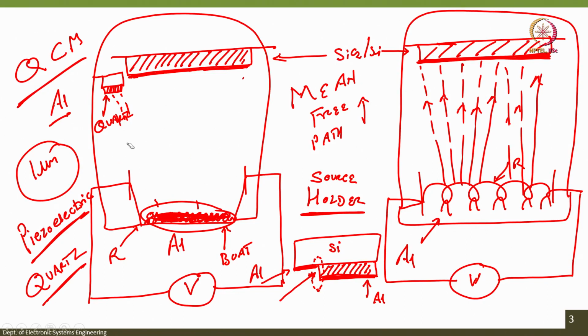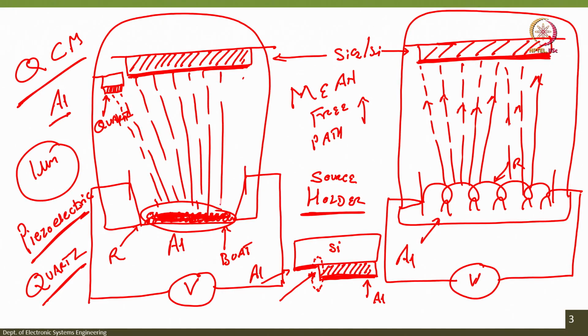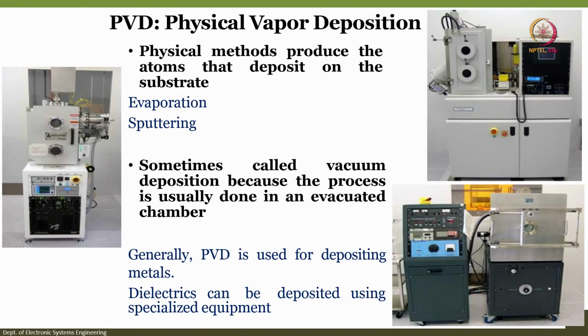So, you wait till the metal gets melted and then you open the masking plate, so that when you start deposition, it will be uniformly deposited. And you can close the deposition not by just dropping the voltage, but by bringing the plate back into this direction. If you bring the plate back, the material that gets deposited will not reach this region, correct. So, that is how things are done. So, let us see the slide.